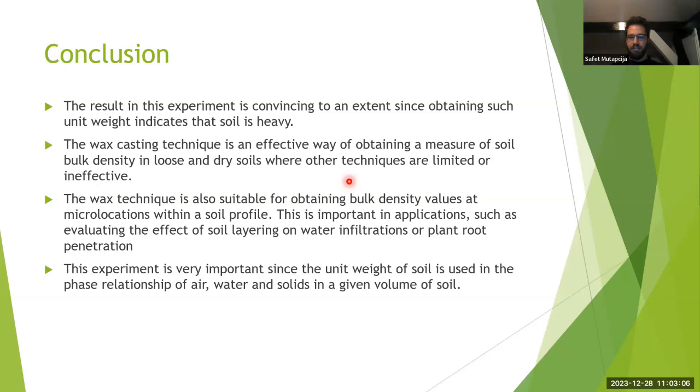So what you do on site, you get lab data, and on site you're going to put one layer of the soil, and then you're going to put water in it. You're going to calculate how much water you need to reach, for example, from 5 to 12. And then you're going to do compaction, and that compaction is going to be best based on your lab results and your optimum water content for the compaction.